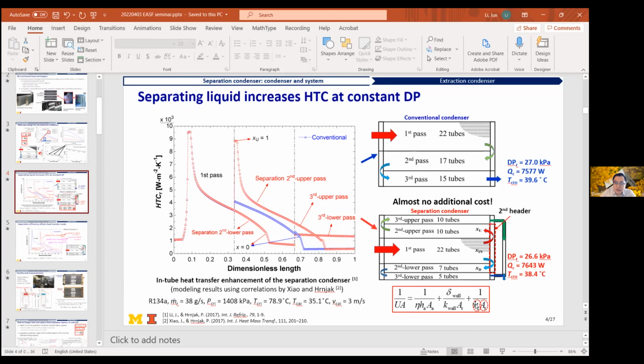And my work, as I circled here, is more on the refrigerant side, how to recircuitry the condenser using the same material, just a different allocation of the material, and use the locally higher refrigerant flow, make it work with the geometry. So I can say that my PhD work changed both of them.